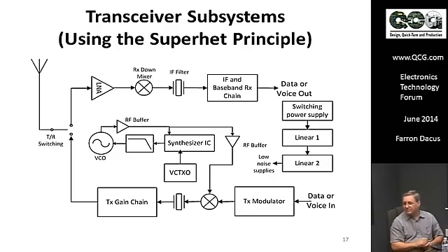Semtech is boasting a transceiver chip that claims to have receive sensitivity on the order of minus 140 dBm. Possible. 150, approaching the theoretical noise floor possible. Right. And how effective can that be? As long as I've been in the game, everybody's been able to design radios which approach the theoretical noise floor, within, say, 6 or 7 dB. You can design a receiver that can have a 6 dB noise figure.